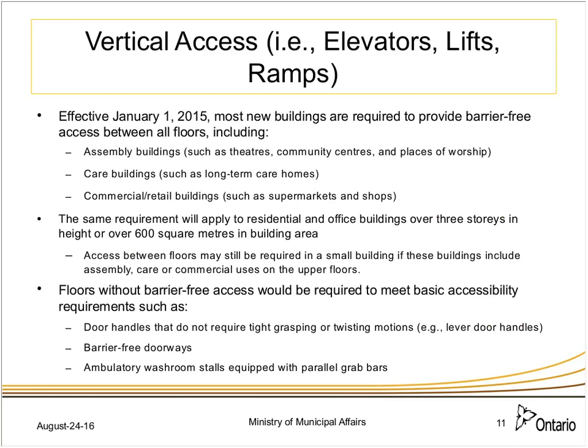We did make a small exception for smaller residential buildings, but on the whole, basically, if you've got a multi-story use, you're probably going to have to contemplate putting in an elevator. So if you had a residential space that you didn't have to provide an elevator to, you still need to do a certain number of things in terms of barrier-free access, but they're fairly logical and fairly low cost.